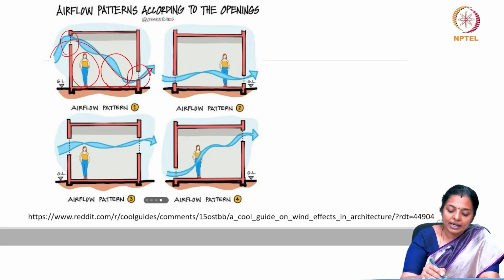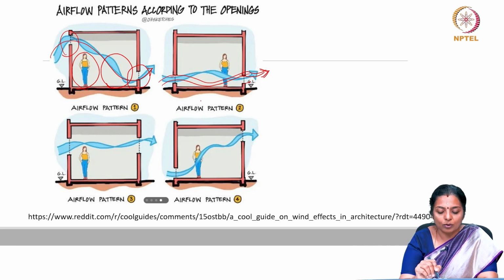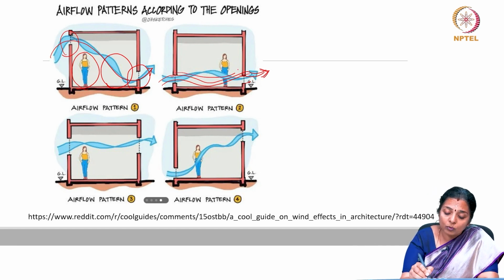When we have inlets at a lower level, there will be a good indoor environmental quality because the stale air is always taken out. However, at working level, there would be complete stagnation and no air movement.